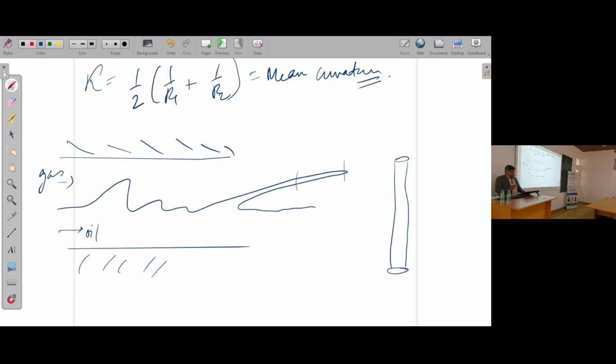If you have surfactant within your oil system, and you'll always have some sort of surfactant, you'll have longer and longer ligaments, because surface tension actually drops when you have a surfactant. It depends on the type of surfactant. Longer ligaments mean that pinch off is becoming more and more difficult. In some systems you would want pinch off to happen, in some systems you don't. So you can actually tune it by surface tension.